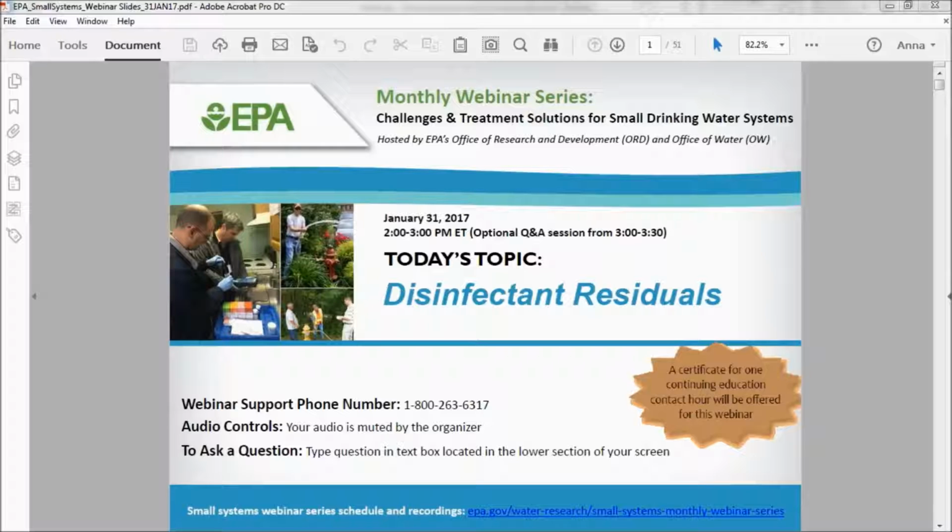Okay. Here's a question. I think it was mentioned in both talks, and I don't think we covered it exactly: how do you ensure proper flushing when sampling? Does someone want to start with that? Talk about the procedure. Yeah, I covered this in my presentation. We developed the calculated flush time procedure, which is based on estimating the volume of water you need to displace between the sample location and the main, and then determining the flow rate while you're flushing. If you know that, you can determine how long you need to flush at that flow rate to displace that amount of water.